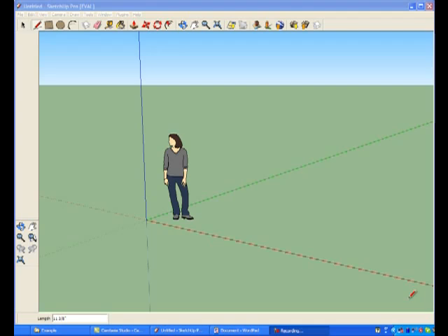Unfortunately, you're going to have to use Google SketchUp Pro because they have moved the CAD feature out of the free version. It is not necessary to have a copy of AutoCAD, but if you do happen to have one, you can simplify things by removing unused layers, setting the proper scale, and adjusting the origin in the event that the coordinate system of the drawing is very large.